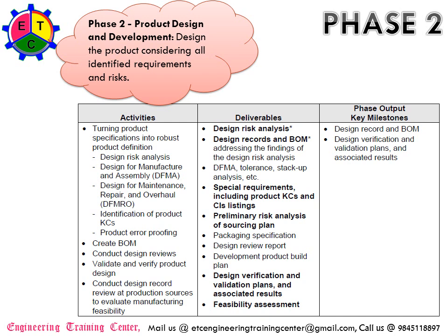And then the next deliverable would be the DFMEA and tolerance stack-up analysis, where you will do the design for manufacturing and manufacturability assessment, and then you will evaluate the tolerances which allow the variability in the manufacturing, and you will conduct the stack-up analysis and see whether, when parts are assembled, they are giving the required function without any interference, form, fit, function working as desired. So those are all the things you will be evaluating, because now the design records like your drawings and bill of materials are finalized,